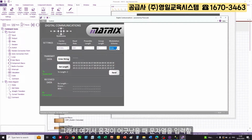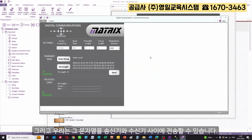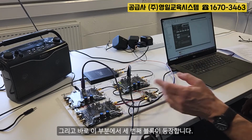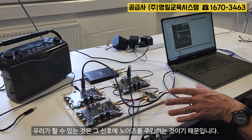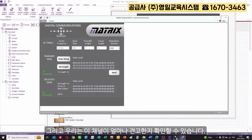So if we take these settings here for on-off keying, we can enter a string, in this case hello world, and we can transmit that string between the transmitter and receiver. And this is where the third Sysblock comes in, because we can inject noise into that signal, and we can see how robust the channel is.